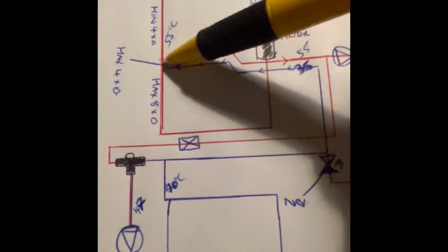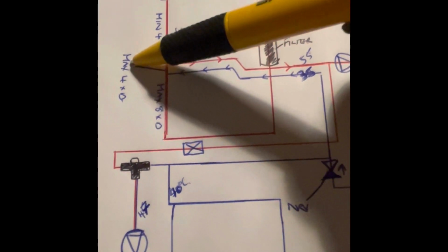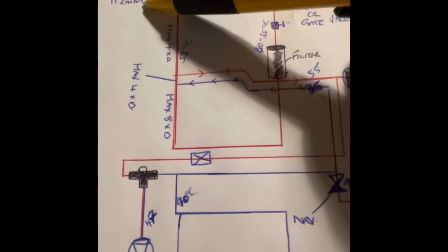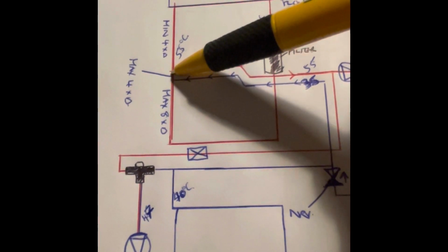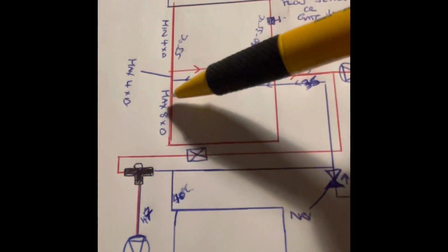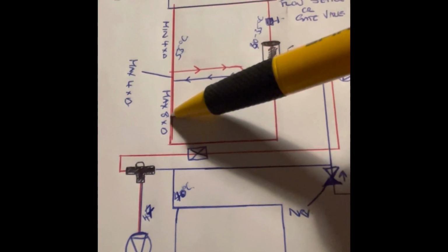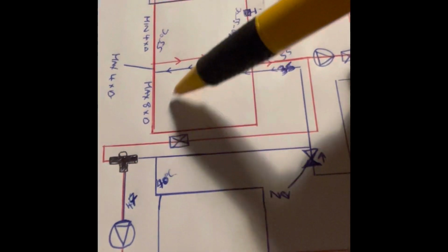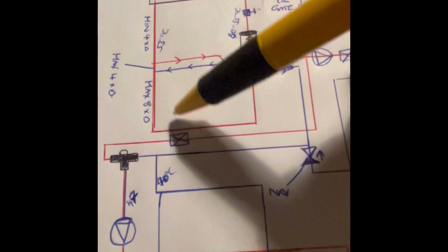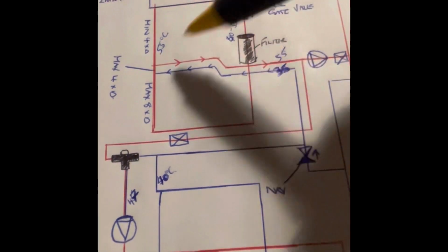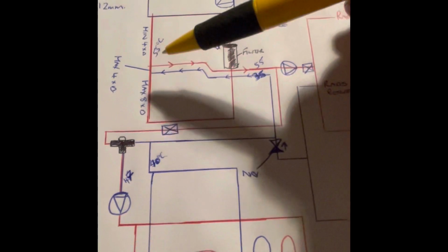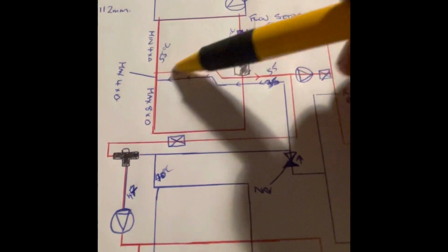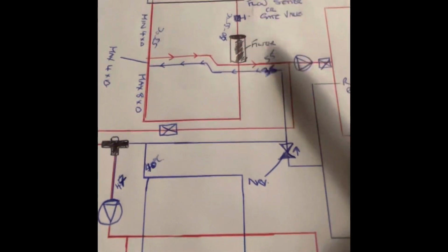Then the distance in between the T's, same again, sorry, maximum of 4 times D, so it can be no more than 112. So realistically, just a little gap in between your T's there will do it. And then on the return side of those, it's a minimum of 8 times D. And that's how you space those. So they could have been anywhere, as long as I got that spacing as it should be. I put them there just as a pipe layout and how I could get it out.